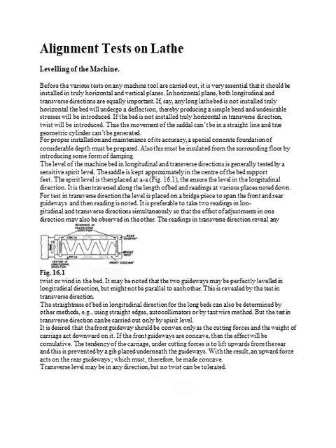At this time, the carriage is kept at the center of the bed and the leveling is checked using the precise spirit level. There is a limit for this level, and it should be within that limit, otherwise it should again be reworked. Okay,